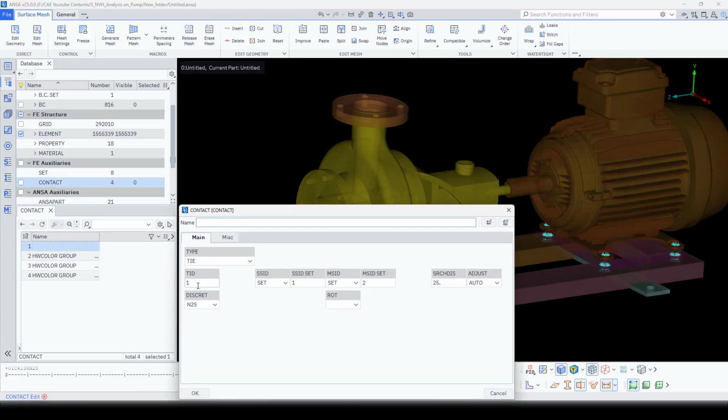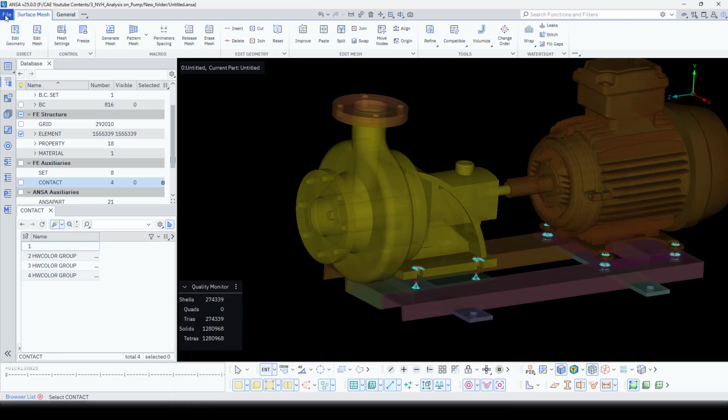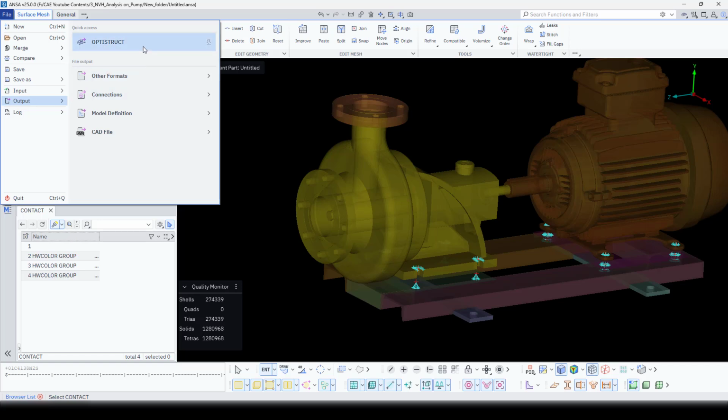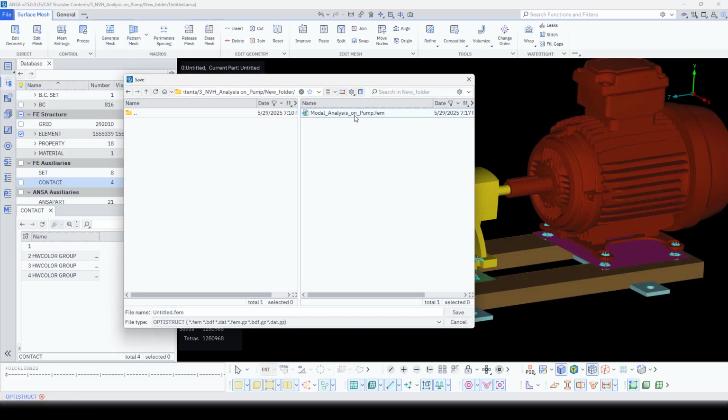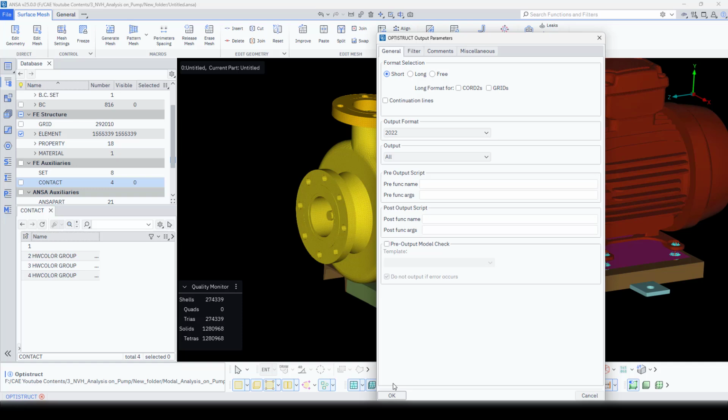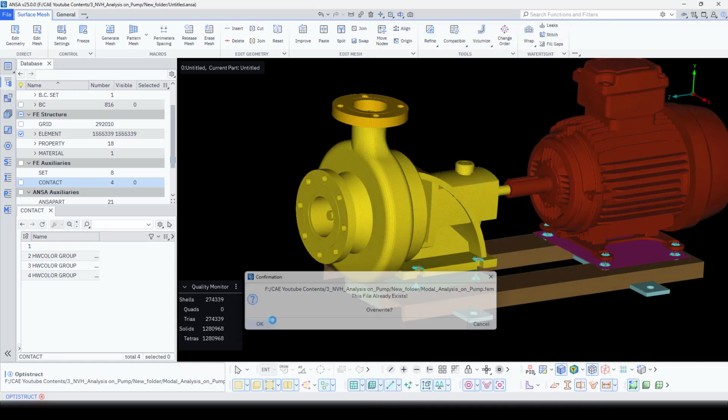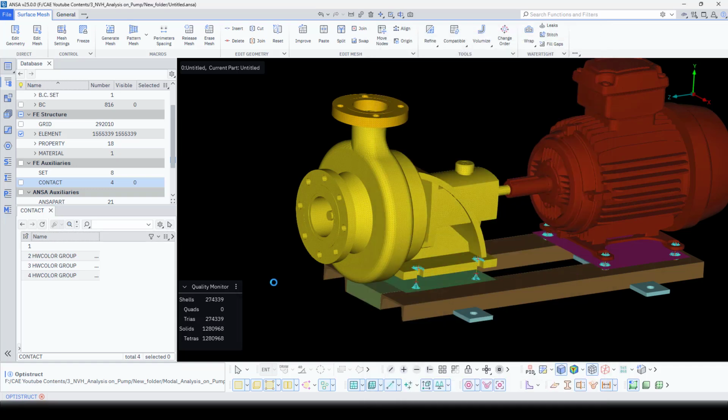You can even still select the surface to surface, but slave should be here grid and the master should be elements. Okay, remember that. For that I did the changes. If you don't do that, you might get the error. It shows master ID is not here, it is not recognized, like that. So to avoid that issue, properly define the sets grid wise and element wise.